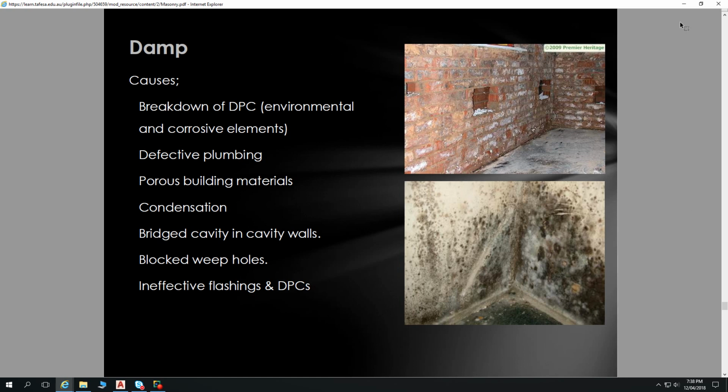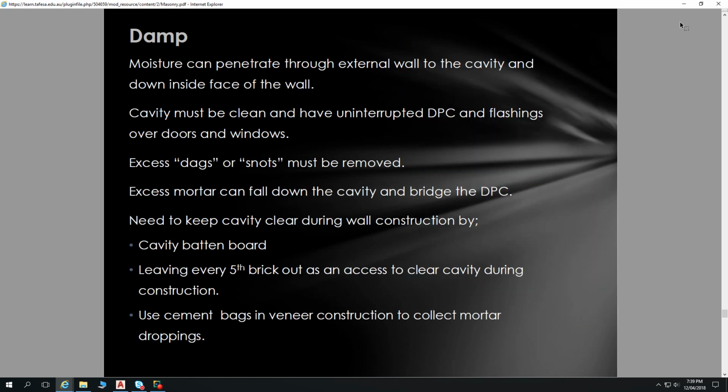Also, I guess you see a lot of damp in buildings where the transition of moisture through a landscape has changed over time. Originally you would have had some areas where the moisture would be directed off in another way, and then people built raised garden beds or whatever and changed all that, and so you have dampness happening in buildings as a result of that as well.